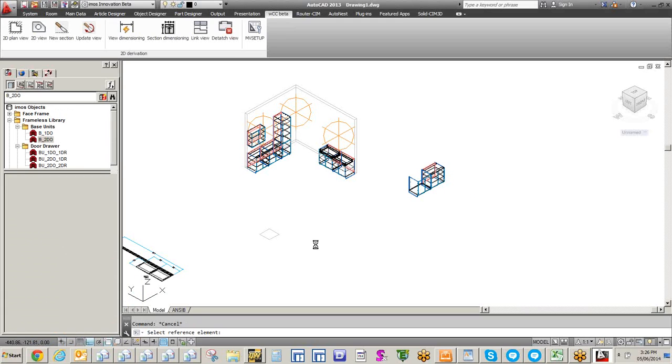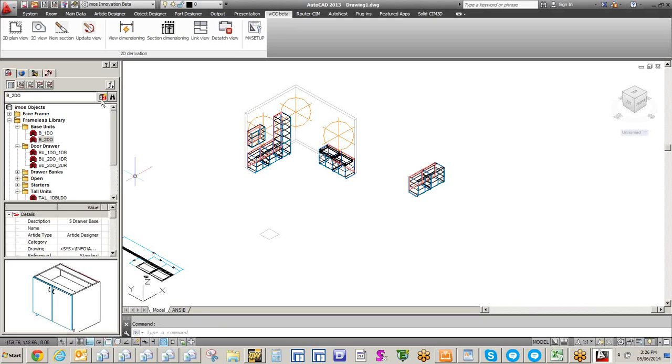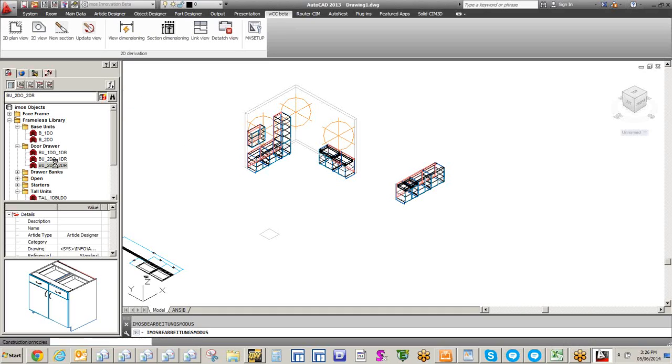If I wanted to do that just occasionally, one or two, or I would have the ability, if I highlight this button and push the quick insert button, in this case we'll tell it that we want to put in some two-drawer cabinets. I'm now going to give this quick placement, so literally it's just as fast as you can hit the button to repeat the commands for whichever items you now select. It's going to place it, and I could just keep going down a list and picking not only this product, but I could also select additional products as we're moving across.